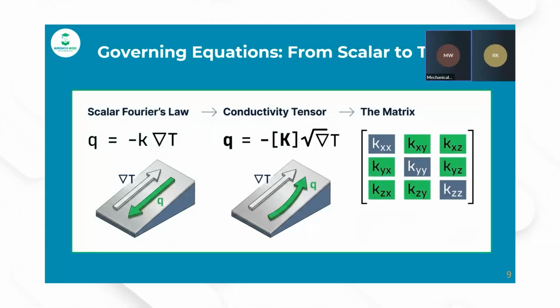Meaning that if the thermal conductivity in xy, xz is much better than yx, yy, yz, and so on and so forth, heat will generally prefer to move in that particular direction because the conductivity is much higher there. So heat will actively try to steer itself toward highly conductive metal foils.